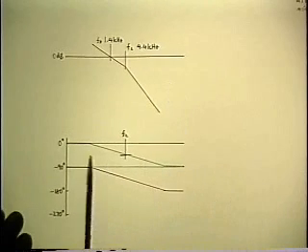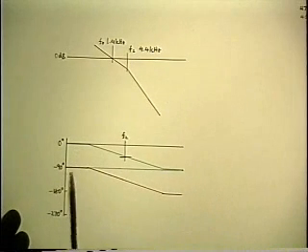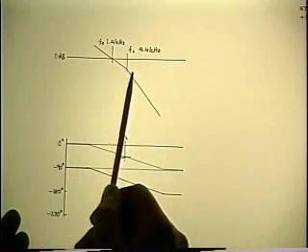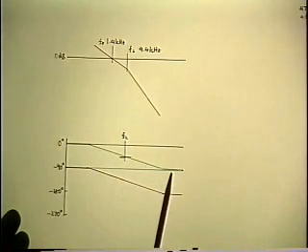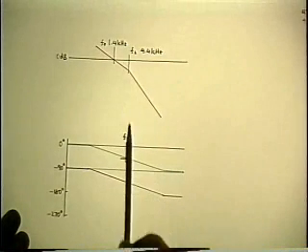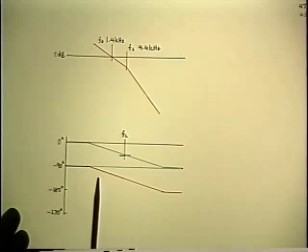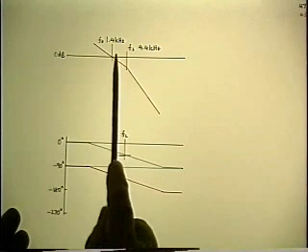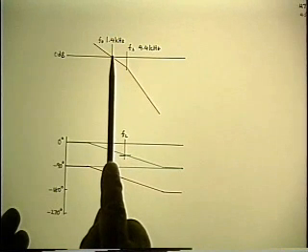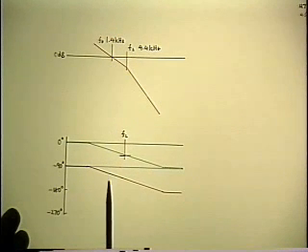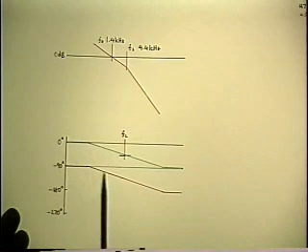And the phase angle that goes with it would be a fixed 90 degrees from the original slope, plus a minus 45 per decade slope centered on the second pole. And the red line is the sum of the two of them. And if you evaluate the phase lag at the crossover frequency of 1.4 kilohertz, you find that the phase margin is 73 degrees. I haven't actually shown that on the picture.